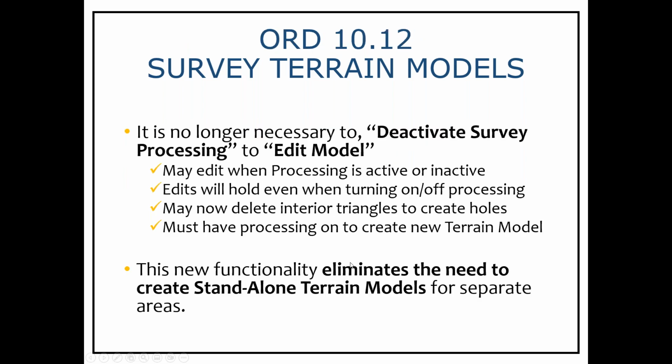So here's where the game changer comes in. 10.12, which is our latest version of ORD, it is no longer necessary to deactivate survey processing to edit the model. So you may edit when processing is active or inactive. It doesn't matter now. Edits will hold even when turning the processing on and off.